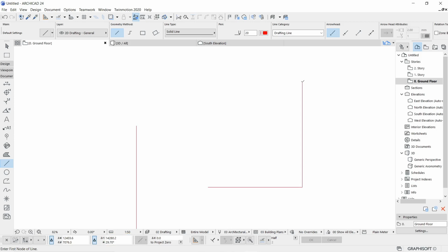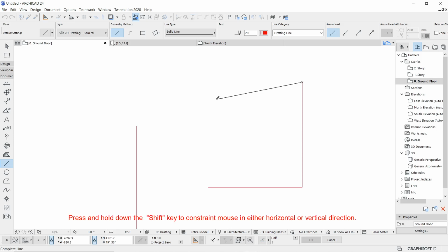Okay, so in the same way, again I'll pick one more point, from that previous endpoint itself. Now this time, I'll show you one more possibility. Now you can see your mouse is very much free so that you can drag your mouse in any direction and the vector is shown in front of you, and you can see the hollow pencil icon. So this time if I drag to the left and hold the shift key, you can see my mouse gets locked to a particular angle. At the bottom of your screen, you can note down the A value. You can check, it is 180 degrees.